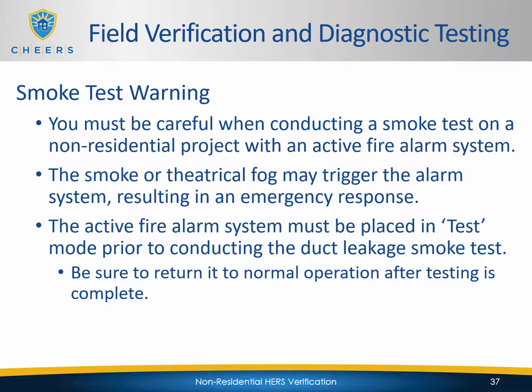For non-residential, you have to be careful when conducting your smoke test if it has an active fire alarm system. You don't see these on the residential side, but on a non-residential, you're going to have these integrated fire alarm systems, and the smoke or theatrical fog can trigger that alarm system, and that means the fire department's going to come out, and it's going to be a big to-do. If you want to prevent that from happening, the active fire alarm system must be placed in test mode prior to conducting your duct leakage smoke test.